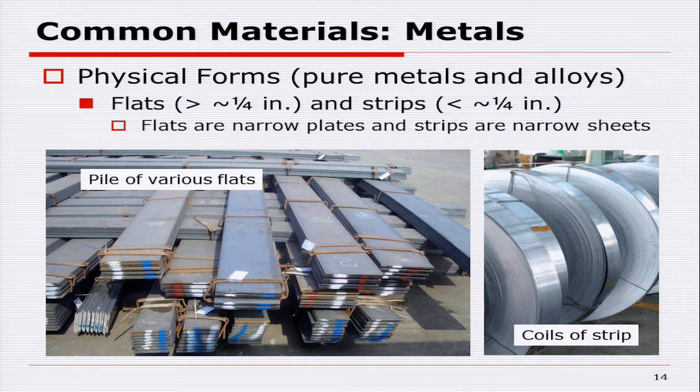Paint tends to pull away from sharp edges or points. So you want to round off that edge. That we can do in our lab, but it costs money, and it takes time and also grinding wheels to do that. It's not a problem in our lab, but it is an issue in industry. If you're working out there making large equipment, you really can't afford that extra time to make an edge round and that extra equipment.